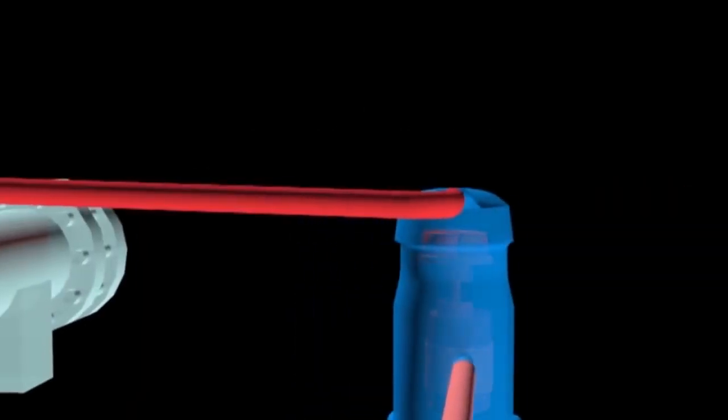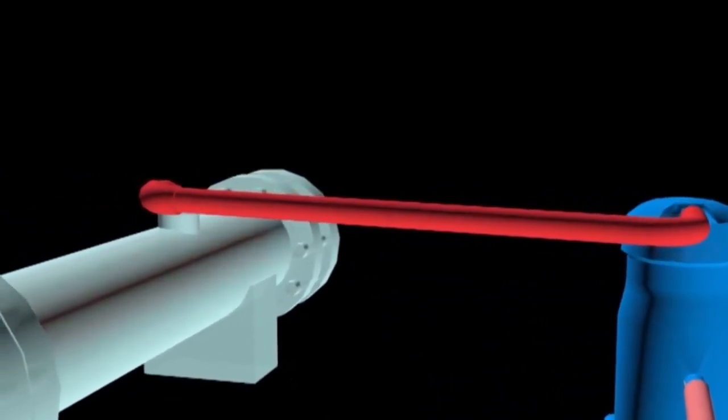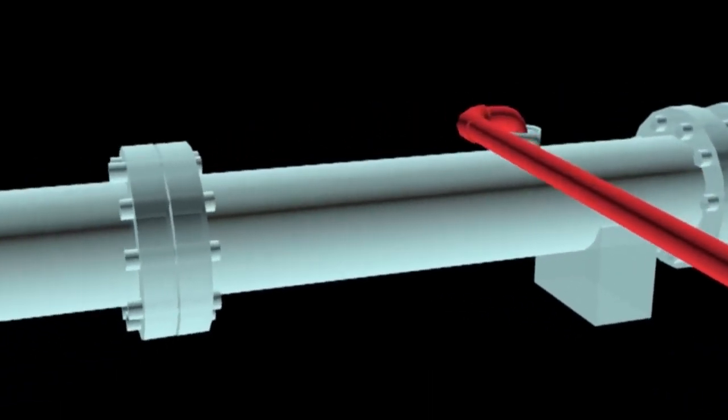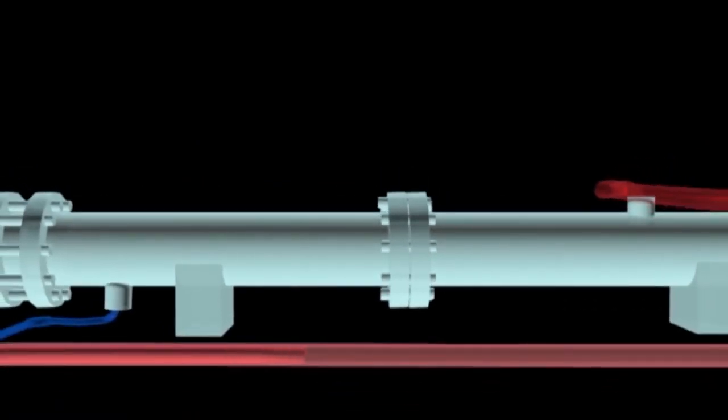Condenser. The refrigerant in high-pressure gas will enter the condenser at a temperature higher than the temperature of condenser water. In the condenser, the heat will be eliminated to the condenser water from the cooling tower through the process of convection and conduction.